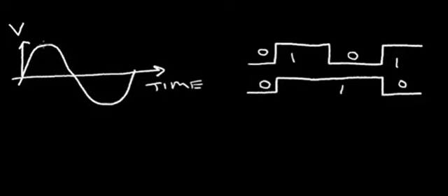Now there are circuits that can analyze this analog waveform. For example, at this point in time, it could analyze this waveform as a digital equivalent. For example, it's at the high point in the waveform. So we may say this is all ones. And at this point where it crosses the axis, we may represent that as all zeros. That's the smaller voltage. And something in between, there'll be an in-between digital code.